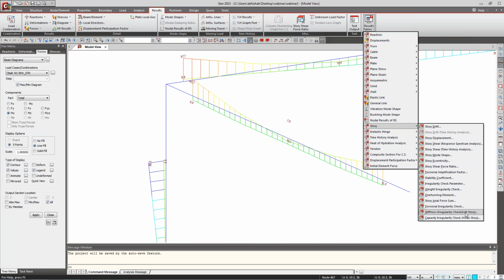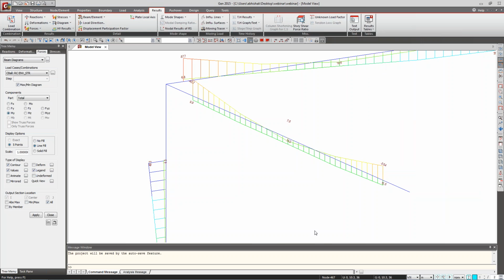Okay, the value you can see only in the 5 points. Mr. Chetan Safaria is asking one question: the moment value in three divisions, can I see it in 5 to 7 divisions? We have one option in the display option. In the left side window, you can see the display option, that is exact and 5 points. If you click on the 5 points, it shows the value only in the 5 points, not more than five. So you have to just click on the 5 points.